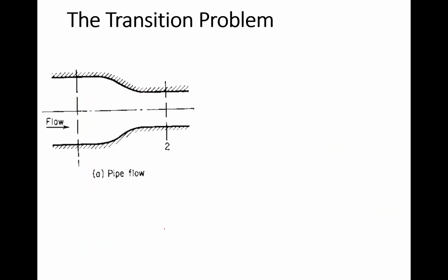Now, before we continue looking at that Bernoulli equation, let's look at a scenario comparing pipe flow to open channel flow. Okay, so what I have on the screen is pipe flow. Flow goes from section 1 to 2. The diameter of the pipe changes from D1 to D2. Obviously, D2 is smaller. As a result, the area of the flow changes from A1 to A2. Conservation of mass, just like before, no changes. It says if it's a steady flow, Q1 should be equal to Q2.